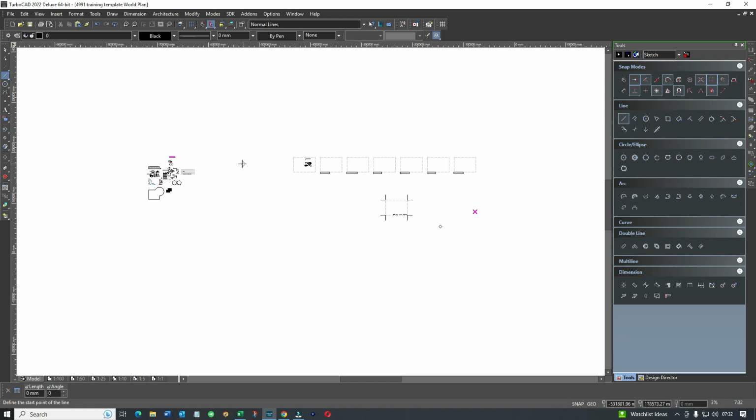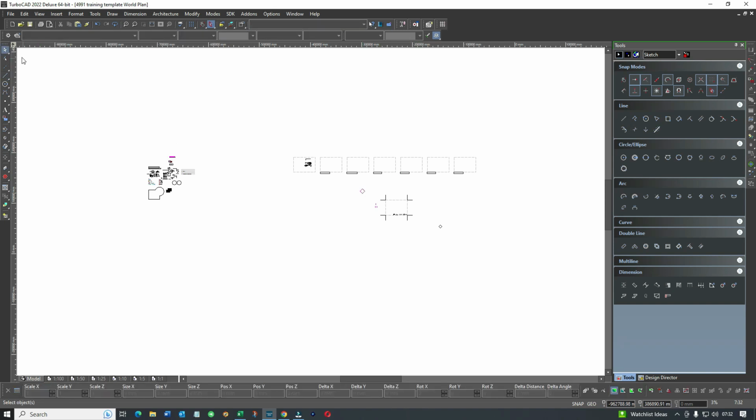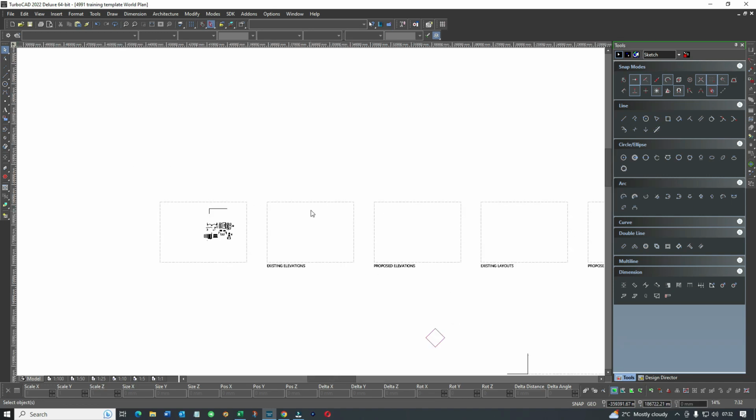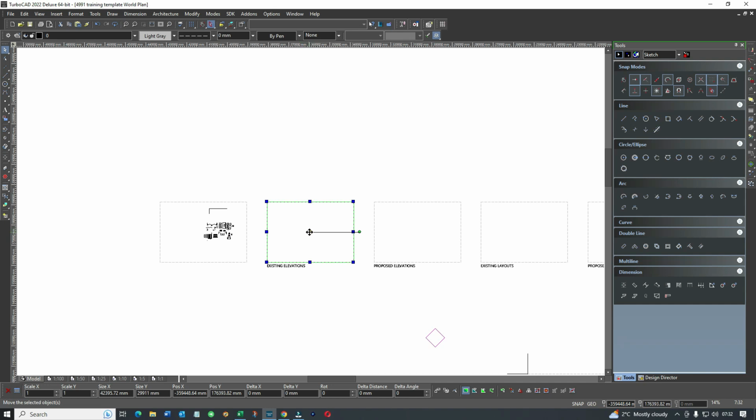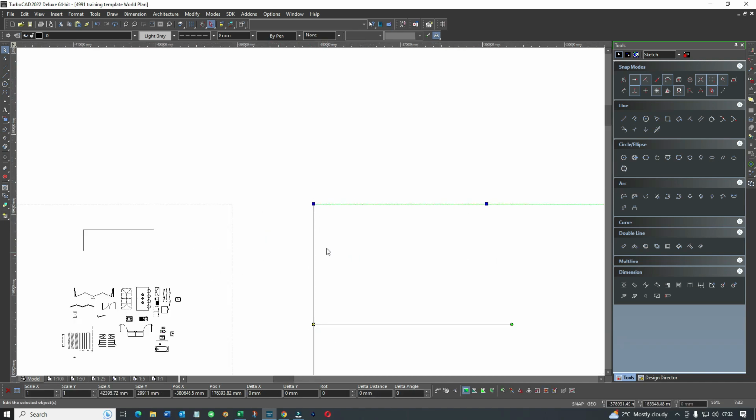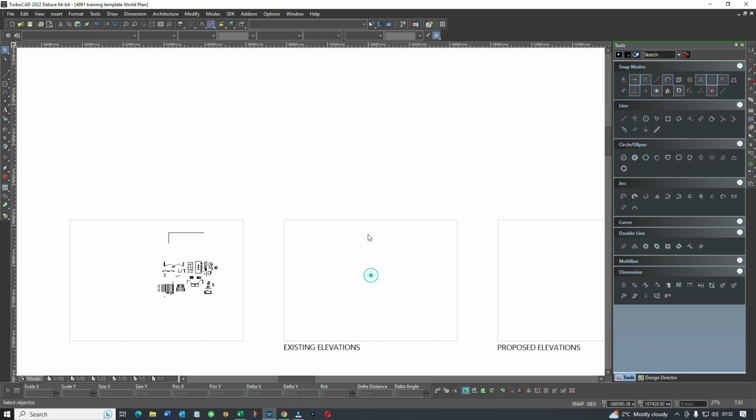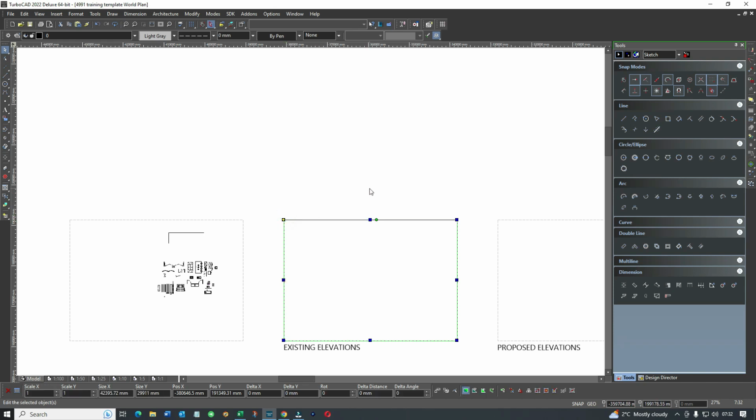Right, and again, remember this was one of the simple ones. I'm doing lines, I'm doing squares, I'm doing something, and I want to grab something else. Hit Spacebar to get to the Select tool, and while you're moving your cursor to pick up whatever it is you're going to pick up, just hit the Spacebar. It automatically moves up. Selection point, that's pretty useful. Selection point was changing from the default, which is the center. You just press the letter D, and the selection point changes. So let's do it again. D, and there you go. Selection point has changed.